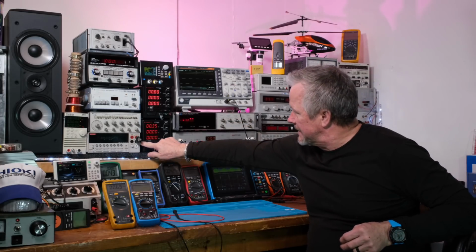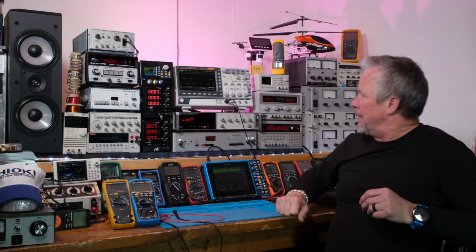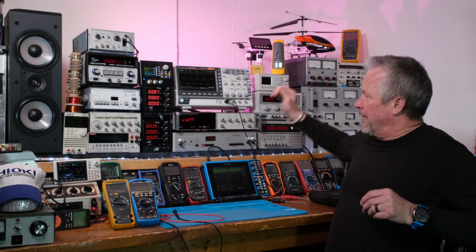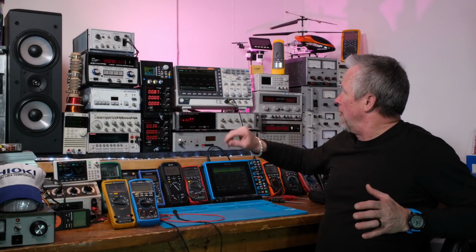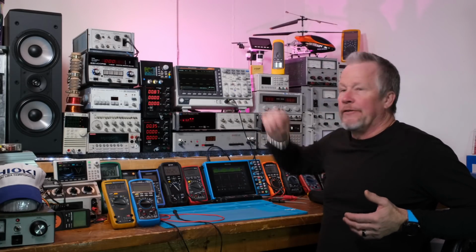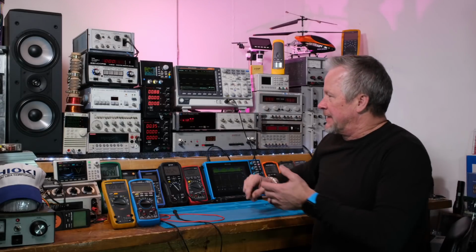In other places, I see the earth ground symbol, like on the power supplies over here, the HPs. All right, so if you float the scope, these things can have a little bit of voltage on them because that leakage current can develop a voltage on that bare metal. And so if you touch this and say touch your generator or touch something else, you could get a shock, and that can be dangerous. So, that's why it's not recommended to float your scope.